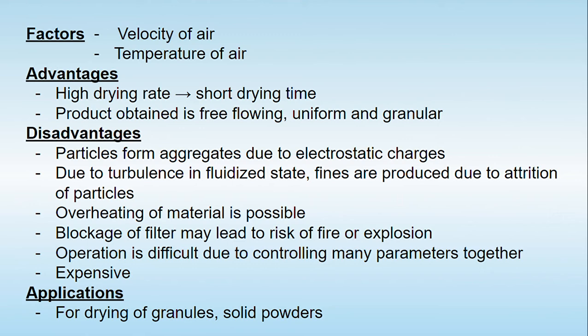Yes, but there are a number of disadvantages also associated with this. Yes, the particles may form aggregates due to electrostatic charges, because the air is coming and might carry some charges, and because of that the particles may form agglomerates. Yes, sometimes due to turbulence. Turbulence means that in the fluidized state the hot air and particles are going to strike the particles, and because of that fines are going to be produced, because the particles strike together and attrition takes place.